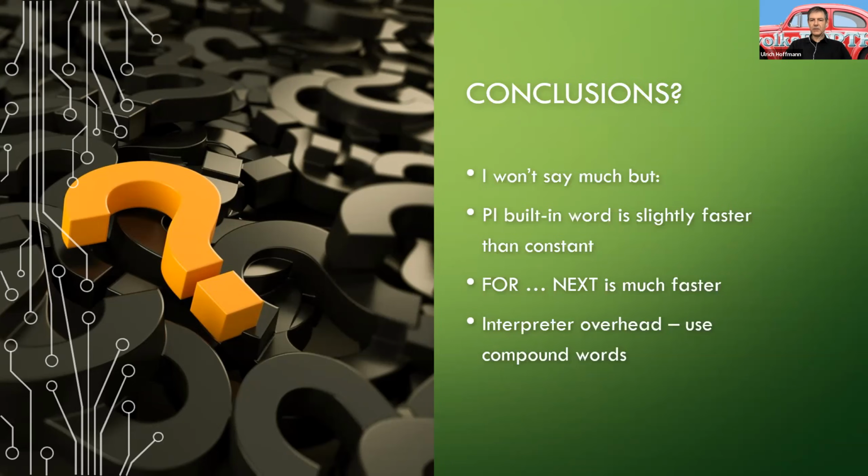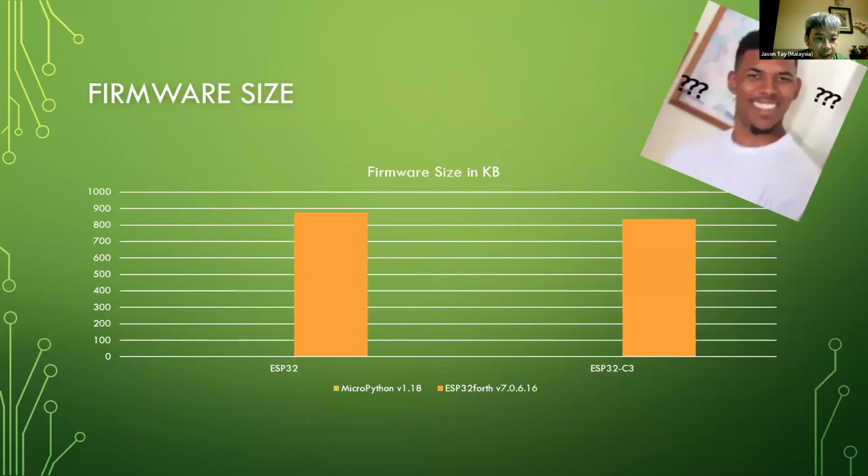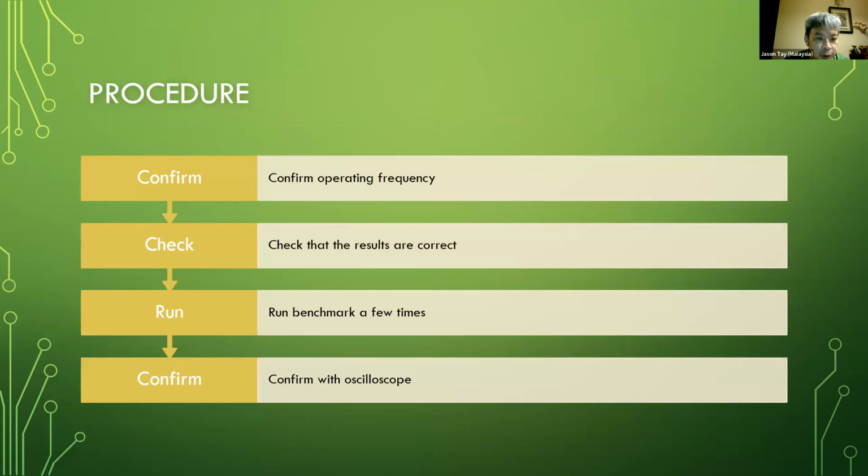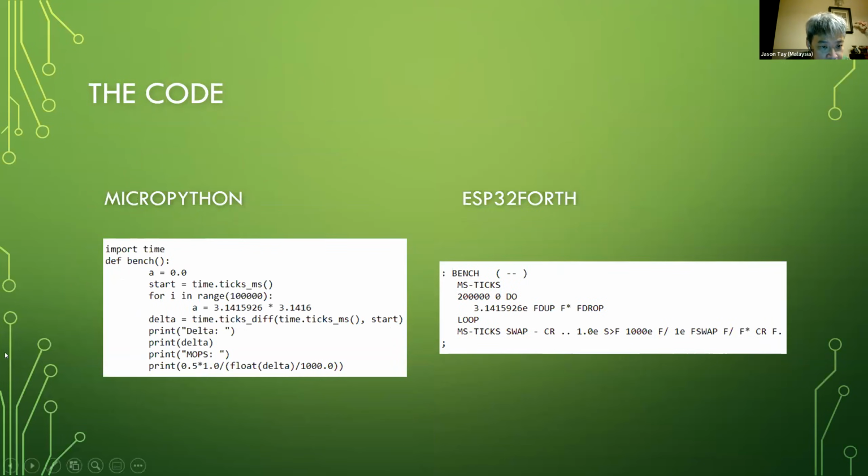Are there other questions? Yeah, Jan is raising his hand. Yes, I have a question about changing the speed from 160 megahertz to 240 megahertz. How did you do that? I think there is a system module that you need to include. Yes, okay, no, I believe it's in SYS.